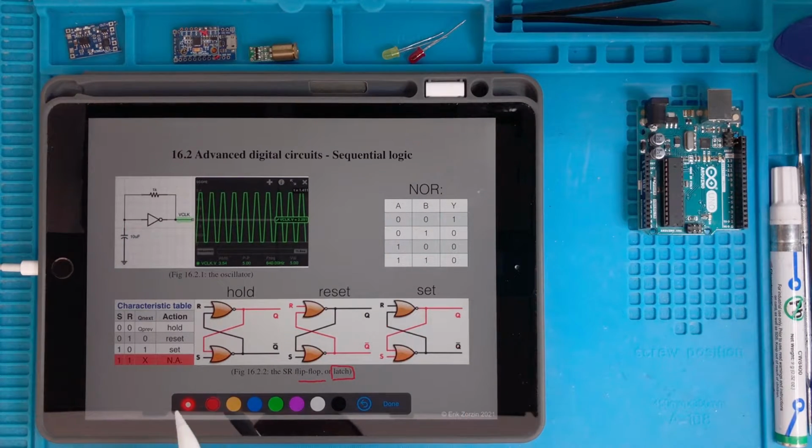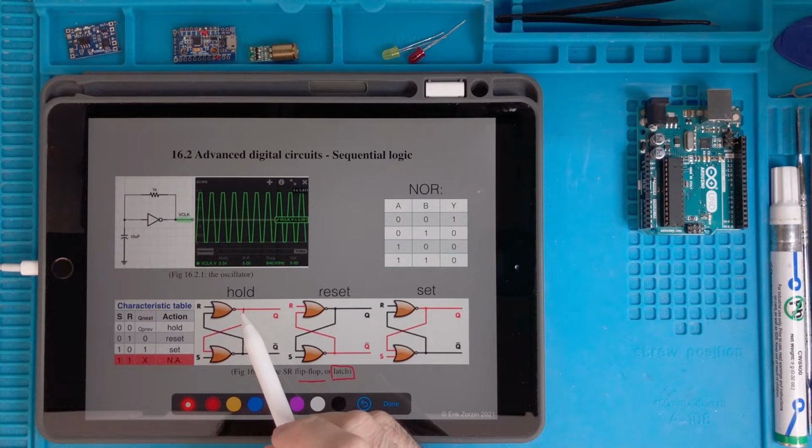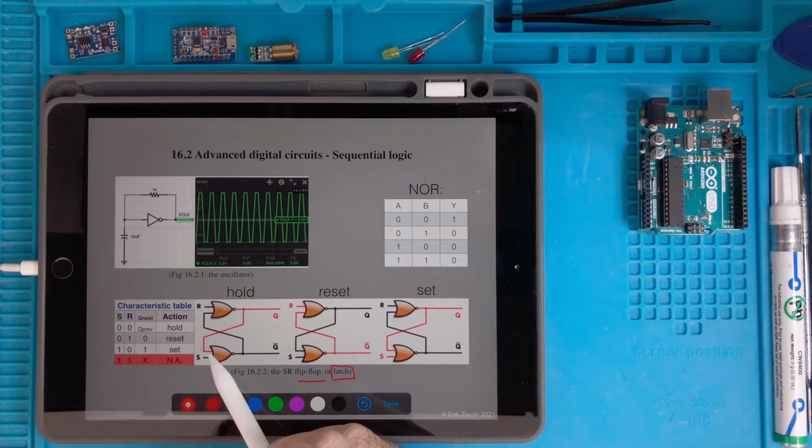So with this in mind, let's analyze this circuit starting from a condition. Let's say from this one. Here in red I highlighted the 1 logic value, and where you see black it means 0. Let's assume that, for instance, we have this output to be 1. Then this value is propagated back here, and we have a 1 at one input of this NOR gate.